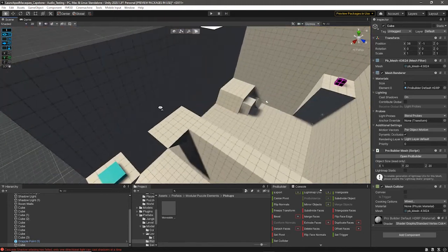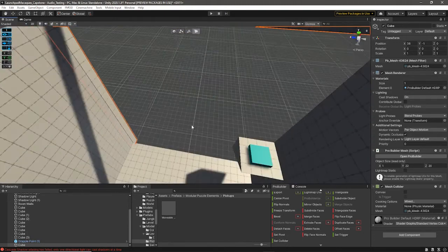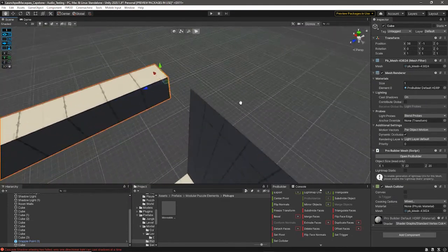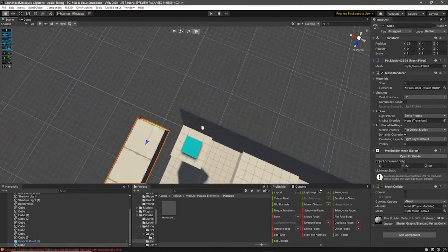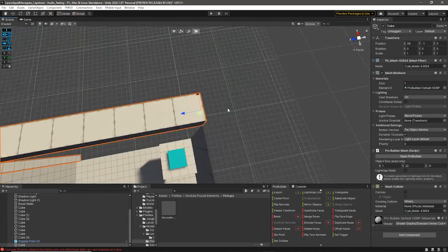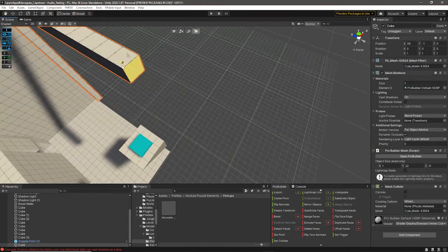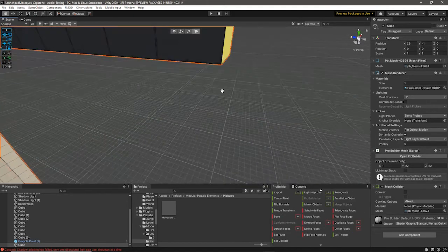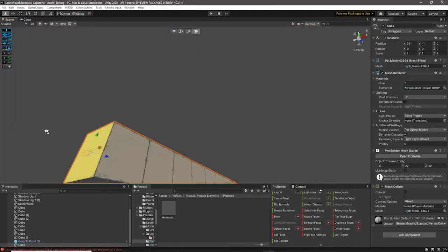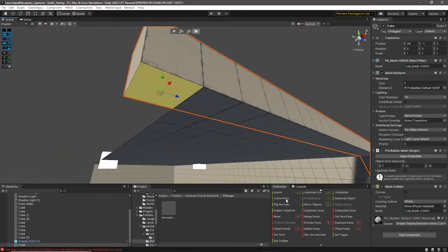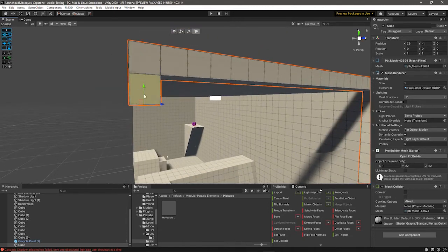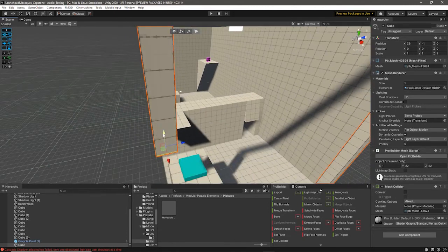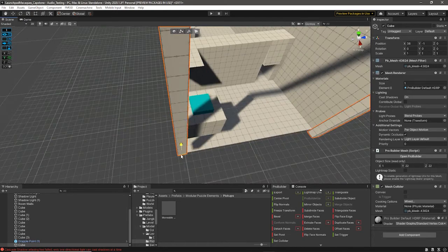So we come over here. Now you can see we've got our frame, so to speak. It's kind of difficult to tell if this is the right spot. Okay, that is the right spot. So we are going to extrude this face, and once you've set up the parameters that you want by clicking this little plus menu, you can actually just click the words and it'll just do it automatically, which is really nice. So I pretty much always extrude by 1, so I can just click it, and I don't have to set the parameter every time, which is nice.